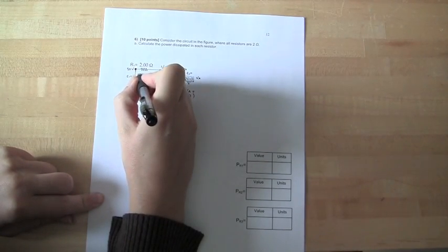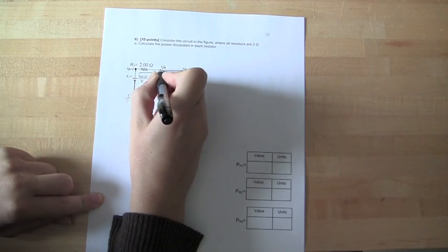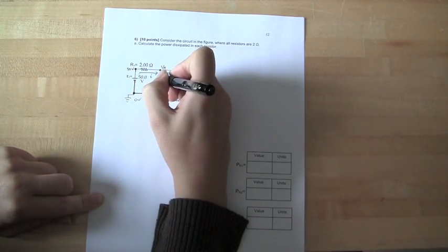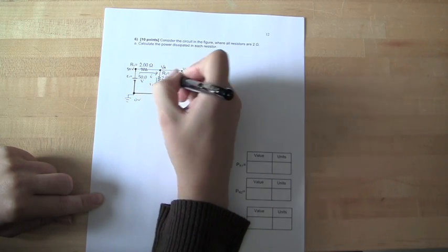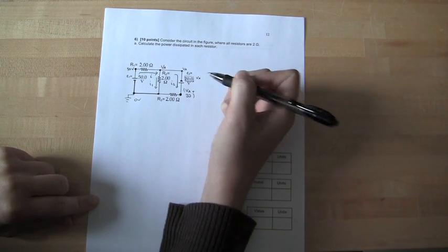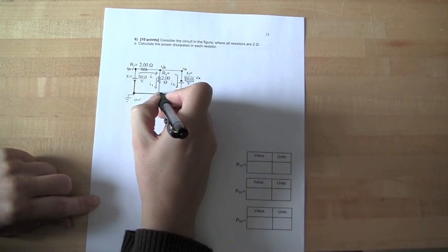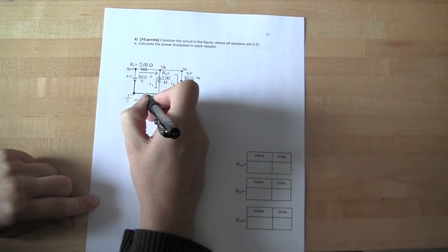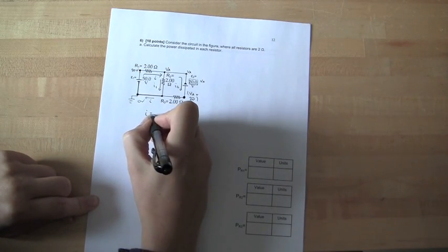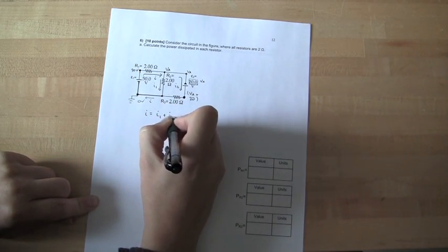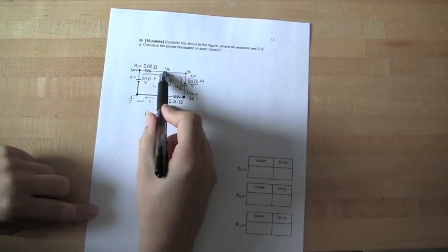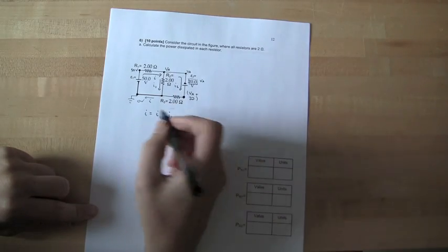So we have some current going into this node here. So some current I, and that's going to split into 2 currents, I1 and I2, through these 2 branches of the circuit. And then at this node here, I1 and I2 will recombine again, and we'll get some current I going back that way. So we know that I is I1 plus I2. This is Kirchhoff's current law applied at this node here.